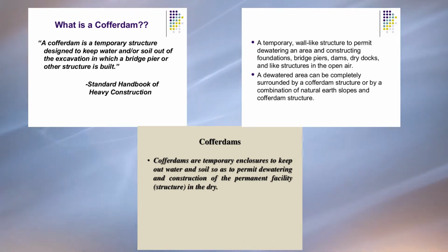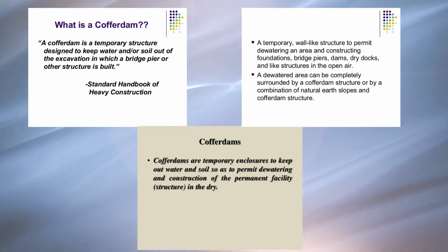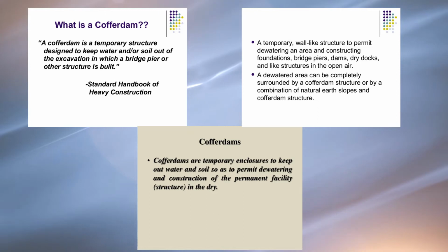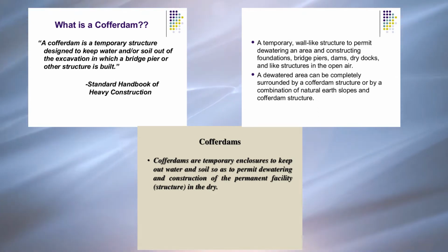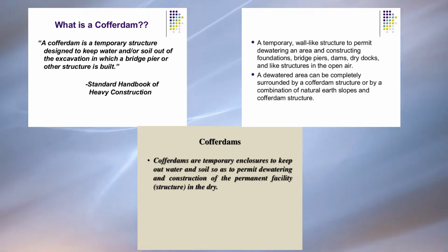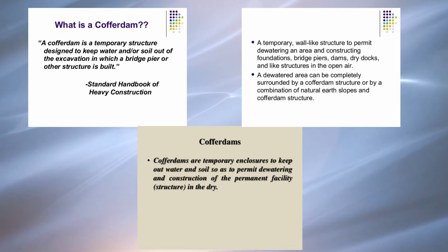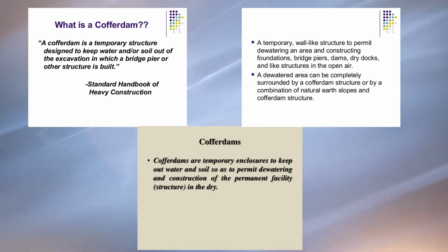Cofferdams must be able to withstand very high pressures and can create hazardous situations if they are installed incorrectly. They are usually constructed using steel sheet piles driven into the ground and supported by internal braces and cross braces.